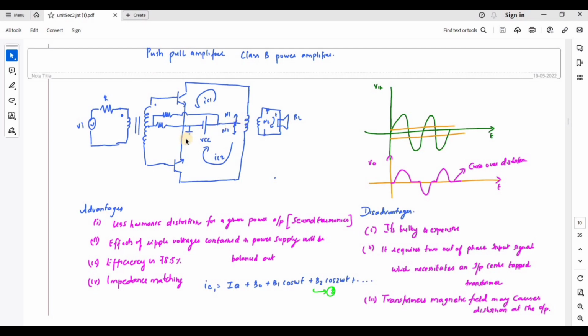The magnetic flux set up by each of these currents will result in opposite flux through the magnetic core. So the net flux in the perfectly matched case is 0. Thus the transformer is not required to handle a large flux due to DC bias current. As a result, the transformer can have a small core size, operating near zero flux.